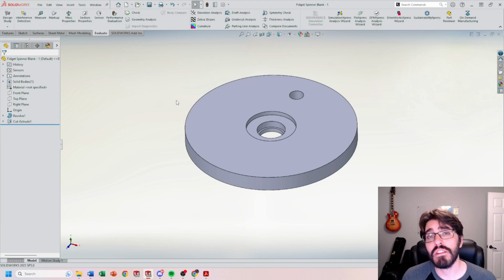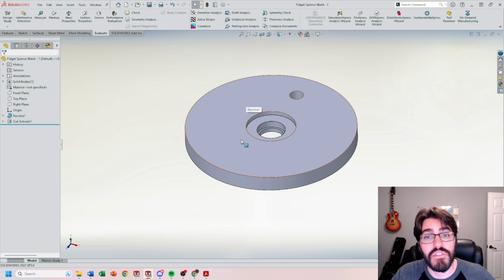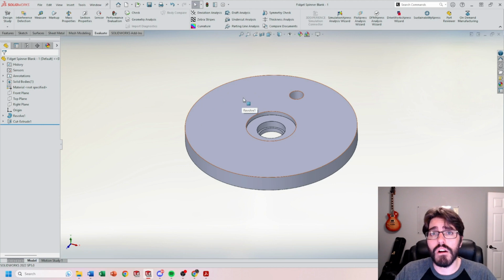In this video we're going to continue on with our fidget spinner case study, and in the last video we left off on the fidget spinner blank, which is going to be our master file or our parent file to be inserted into our design files, or our child files. So we're going to make this fidget spinner blank, and then we're going to insert it into a SolidWorks design file or part file, and we're going to now draw the 3-spoke spinner or maybe even the 5-spoke spinner, whatever design that you're working on, out of that parent file. So all these files will be our child files, and this will be our parent file.